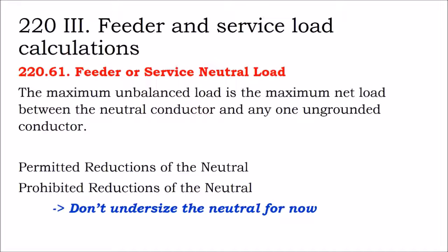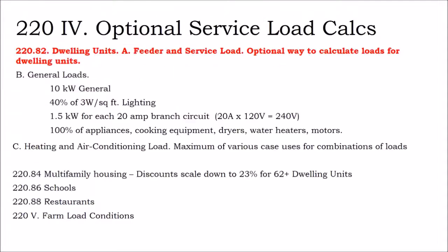If you do undersize the neutral, you may save a little bit of money, but not as much money as a design mistake. If you do all of your conduit calculations for a full-size neutral, you're not going to have any design changes if, when it comes time to order the material, your supplier comes back and says, actually, you usually undersize the neutral in this location, and you decide to do a design change. But if you're just beginning, don't undersize the neutral for now.